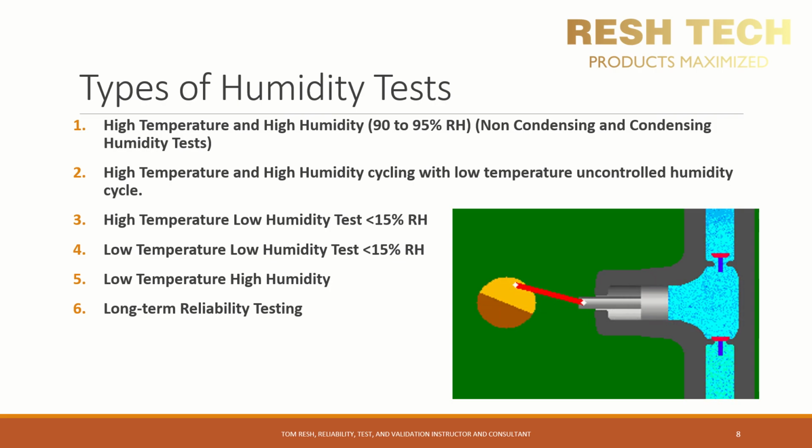The image to the right illustrates a diaphragm pump, which demonstrates the diaphragm pumping action that I'm referring to with the contraction and expansion of a pore seal design. So keep this in mind when planning and designing your sealing strategy. Additionally, if the low temperature portion of the cycle is below freezing, you can evaluate the impact of what happens to a component of your system as the temperature decreases and water condenses on your system and then freezes. This can cause cracking and degradation of different parts of your system and is a great test to keep in mind for assessing humidity and freezing temperature environments.